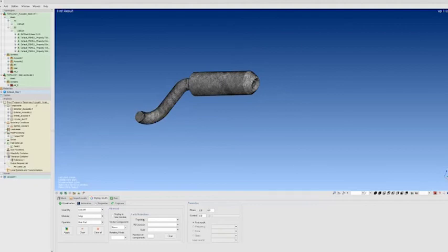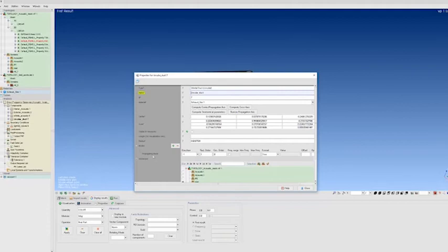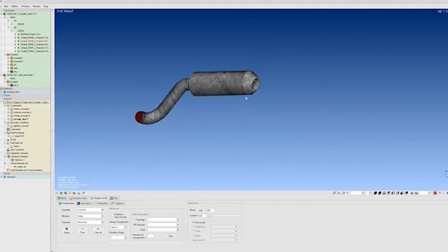Then we have what I call interior acoustics. This is just an acoustic region, which refers to this exhaust gas material. Actually, we could have spatially dependent material properties according to SC-Tetra calculation results. And this is how it looks like. So we have a 3D mesh, which is basically the entire muffler, so inside, and also part of the outside to capture the jet here. So this is our acoustic component, and we have our Lighthill volume boundary condition. So basically, this is where our sources will be. And this refers to the aeroacoustic sources that we already computed.